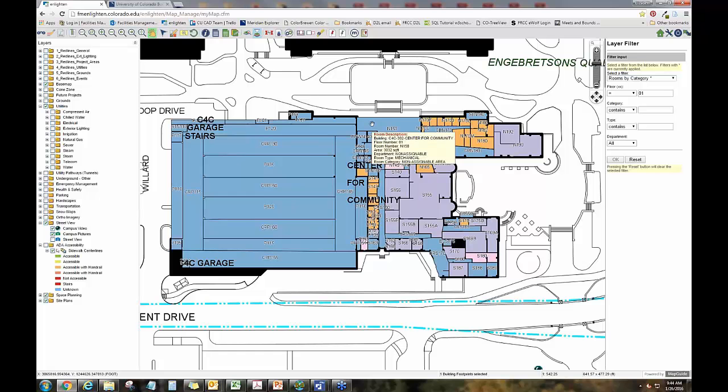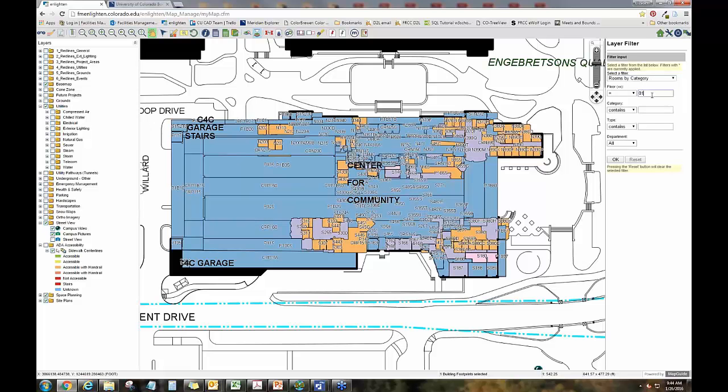And in order to get the geometry to match all the data to, we're actually XREFing our AutoCAD floor plans into a campus map and then georeferencing all of those XREFs and then using that data to give it base points to pull the geometry out of the AutoCAD files into the GIS, and then matching that back together with the Famous data. So it comes out as a map that looks fairly straightforward, and you've got polygons and data, but it really took a lot of manipulating and batching back and forth to get all this data into something that we can quickly do this, reset, and let's look at the second floor.